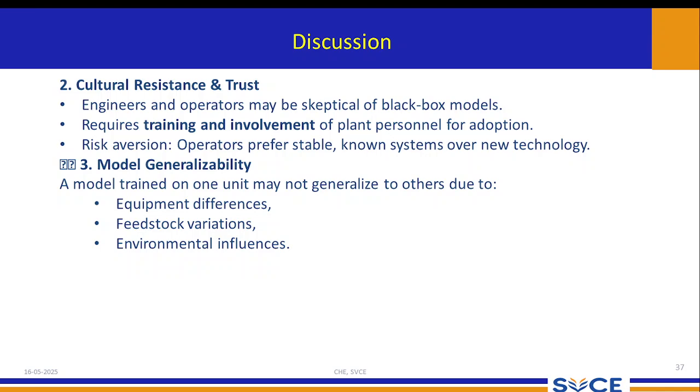When I was doing my master's, I was asked to test the characteristic compound analysis of treated effluent, treated sludge actually, using an advanced oxidation process with ferrous sulfate and hydrogen peroxide. After the sample was collected, I wanted to measure the COD and BOD values and the compounds present inside the treated sample. When I went for testing using a GCMS, gas chromatography mass spectrometry, they gave a procedure to follow, saying the water content should not be present in the sample. That is the requirement of that particular equipment.